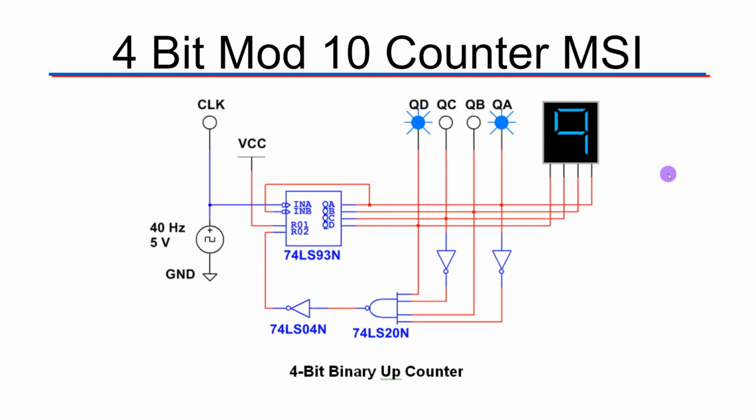So this is the design inspiring what we're about to build. Again, in Multisim, if we built this, it would look approximately like this. We have most of the pieces we need here. Specifically, we have a 4-bit counter provided for us, medium scale integration, which just means we're being provided the working component instead of building this out with flip-flops, right?